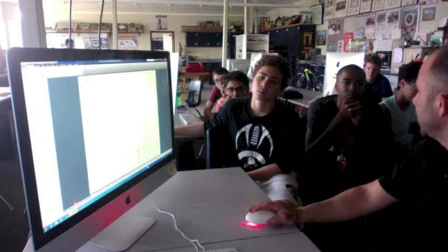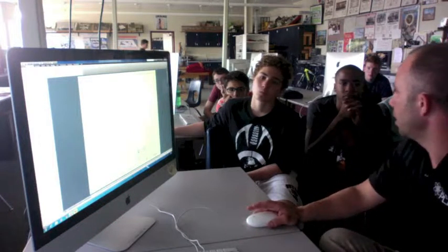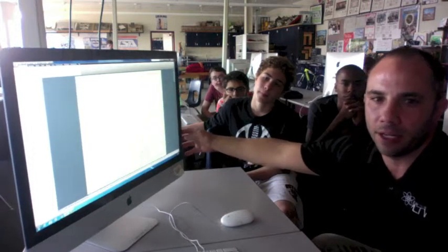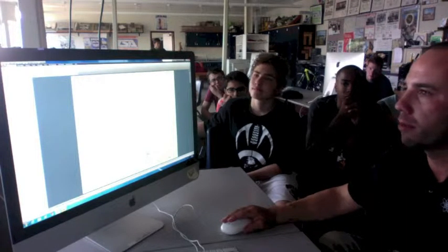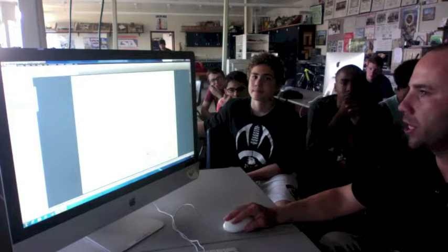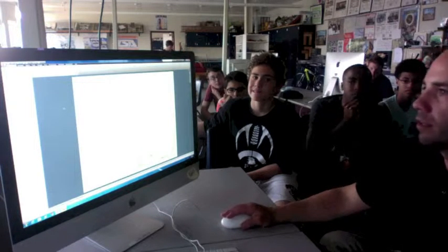So here, it's a C-size sheet, meaning it's probably 17 by 22, a little too big. So I'm going to make that sheet a little smaller. So I'm going to right click over in my project model browser, edit sheet, and I'm going to pick A. A is 8.5 by 11. Okay, now I'm ready to